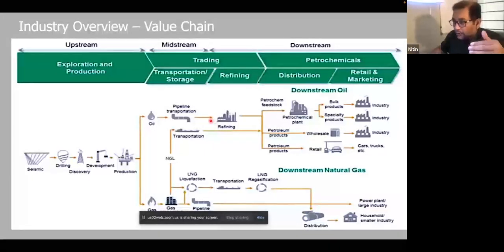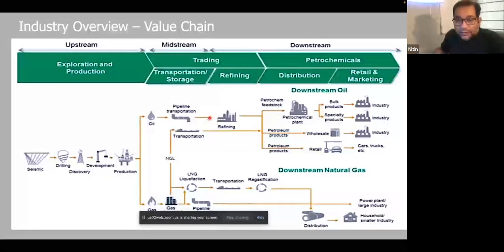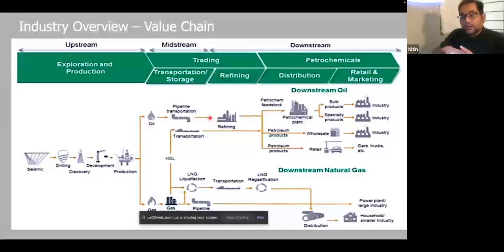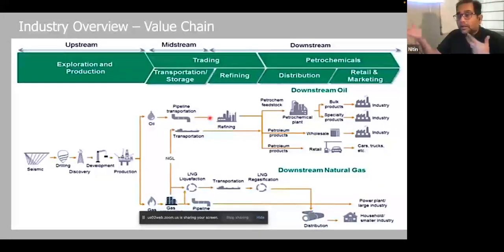So similar thing, when you want to control operations to run at a particular flow, temperature, and pressure set point, the control systems are capable of doing so with respect to all kinds of disturbance and variability happening from internal to external systems. So internal disturbance can be variability in the process. The flow can go up and down. Shutting of a valve, opening of a valve can create disturbance, and external disturbance can be ambient temperature variation up and down, atmospheric pressure up and down. There could be rain, or vibration or wind flow. All those things are disturbance.